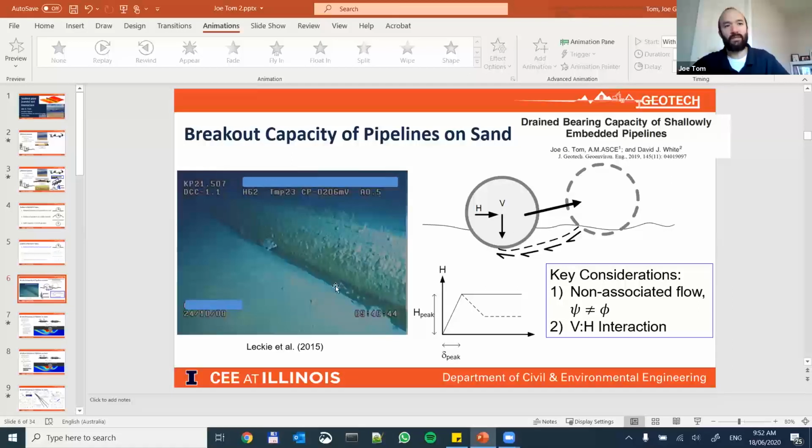The other thing, which was pointed out in the paper by Simon, is that there are issues with roughness. There are also issues, which aren't geotechnical, where sediment transport changes and spans form, which actually reduces the load on the pipeline. So I only talked about the geotechnical part of this, but these sediment transport changes are quite complex, and the interactions with the overall pipeline design are quite interesting.